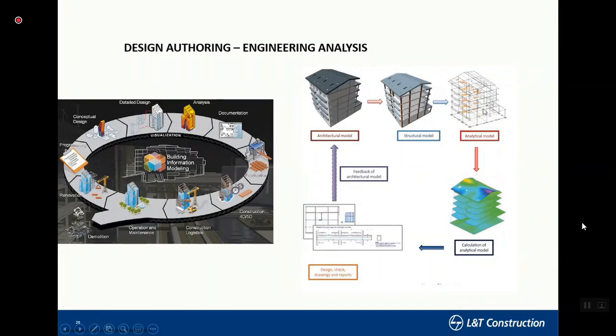Based on his model, the structural person will do the structural model. And that model is imported into the analytical tool such as STAAD or RISA, and we do the analysis. From there, we generate the various reports. And once everything is satisfied, we generate the drawings. So basically, we don't repeat. The basic 3D model is moved into the analysis tool where you don't need to remodel again. You apply your loads, do the analysis, update the model and give it back to the authoring tool. So that means I am saving time, and the overall project time gets reduced.